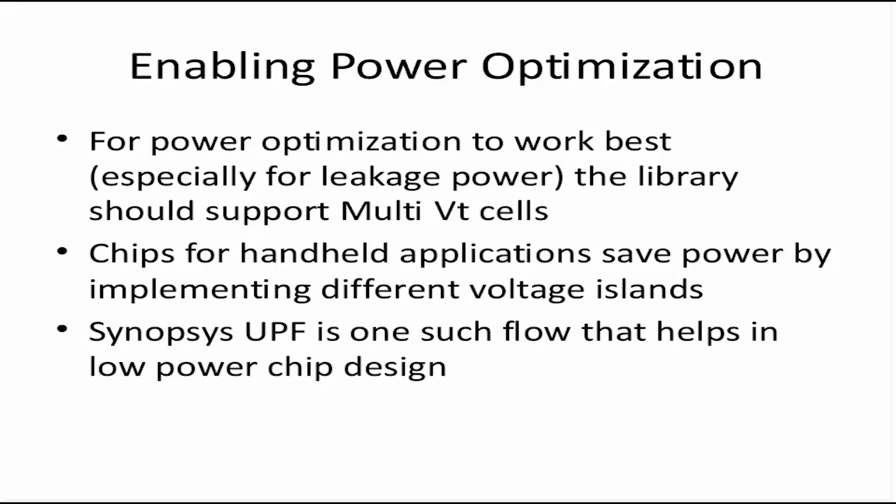It will have a baseband processor. It will have an application processor. The application processor is usually what we see in the specification as denoted by quad core or dual core, and so on. There will be again a baseband which will decode the terrestrial signal, the GSM signal or the CDMA signal.